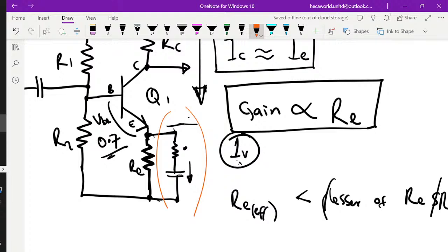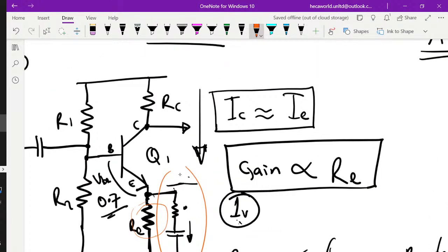So what I want to do is have a signal that goes into the emitter circuit, and that signal is modulating what is happening in my emitter circuit and causing the gain to change according to the signal that is coming into it. So with that, I can create an amplitude modulation. And then if that's my video signal, I can transmit that video signal and receive it on a TV that corresponds with the oscillator.